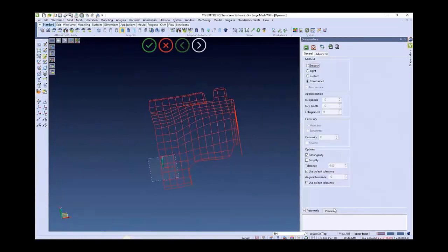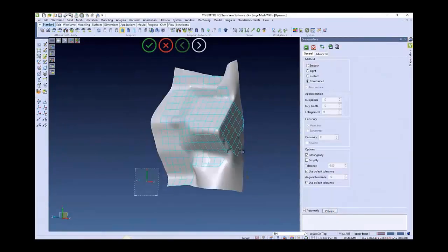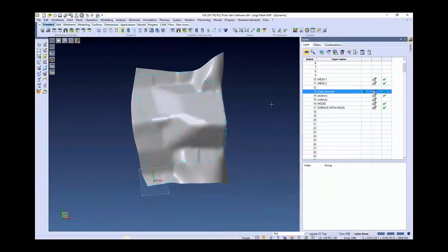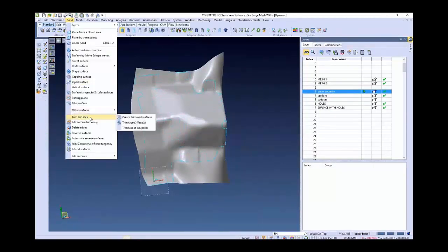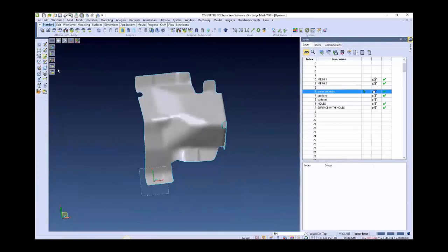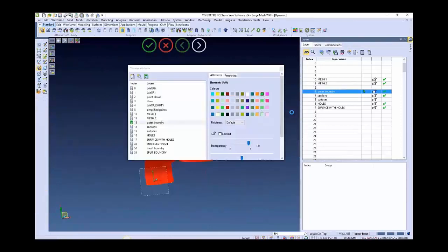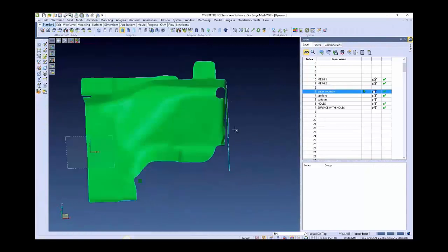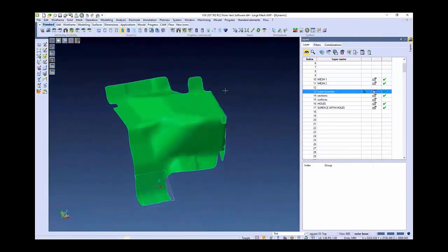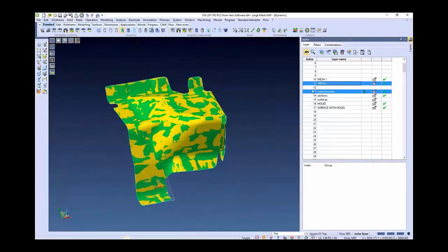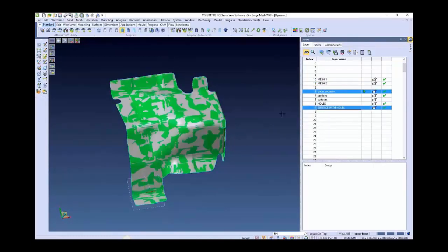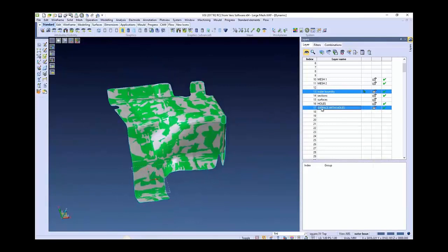You can also use a drape surface and get one much faster. Obviously, results are going to be affected. Create a trim surface, use that outer boundary. And we'll see the difference here. Turn on that other mesh. And turn on our surface.